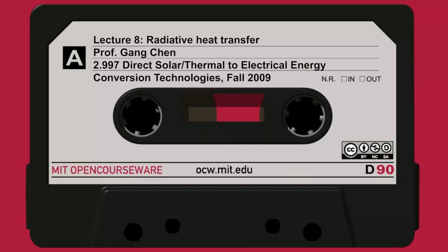So that's the emissive power, and Planck's law of blackbody radiation could be written either in the intensity form or in the emissive power form. I apologize that I missed the c squared in my first lecture. If you go back to the notes, you can add that. So that's the intensity and emissive power, and this is pretty much what we talked about before.